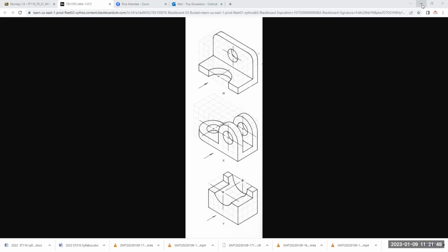Can't really see the grid points, but I know it was 16 along the bottom. My primary method of drawing is just to aim and shoot, right? I just use that green marching ants thing, get it vertical. And if I want a certain distance, I just type in the distance and hit enter because I'm already in the line command. Line command is just kind of continuous. So it looks like it goes up. Oh, I can actually see it: 2, 4, 6, 8, 10 inches.